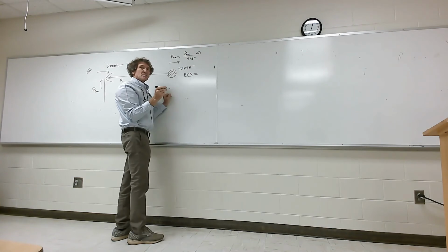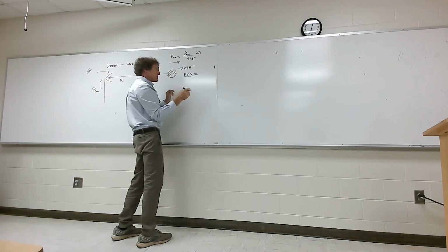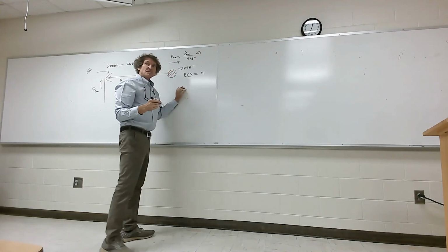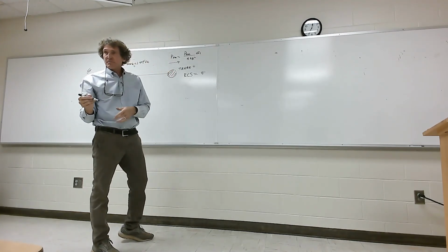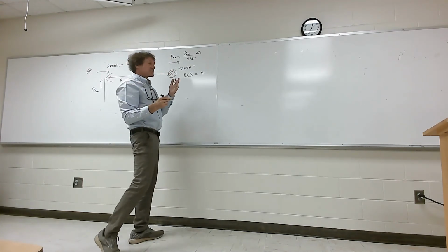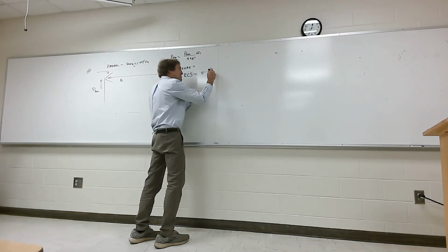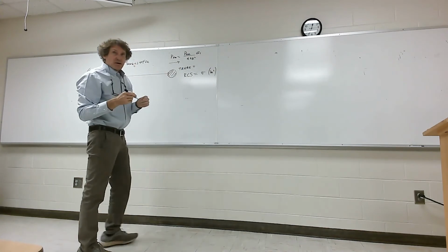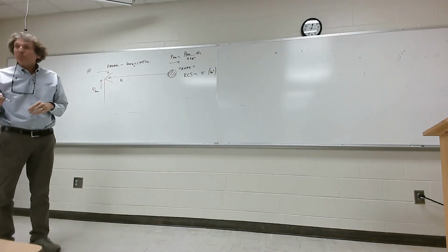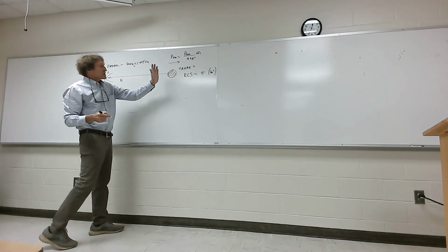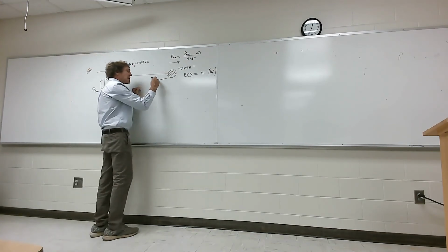The symbol Dr. Wentworth's book uses, and most books use, for radar cross section is sigma. I know we use that also for conductivity, but it would be very obvious that this is a radar cross section because the units are meters squared. Right? So that's how big it is electrically. Now, when this signal hits the target, it's going to re-radiate power.